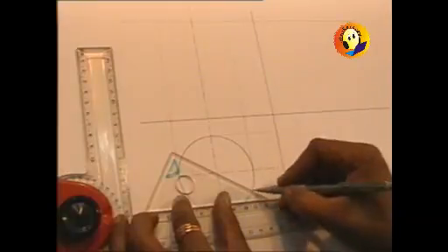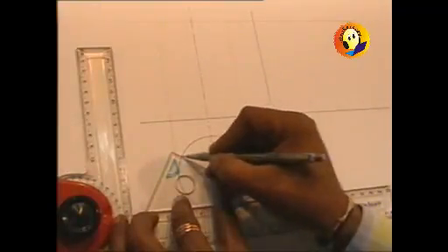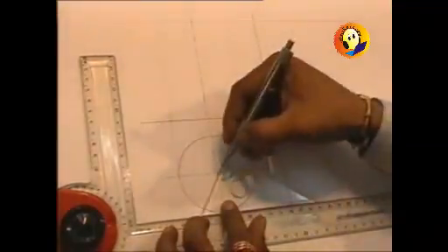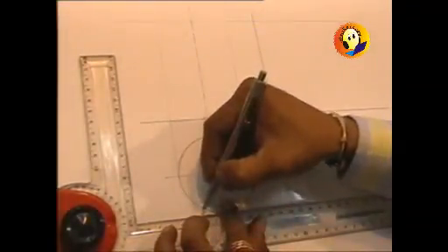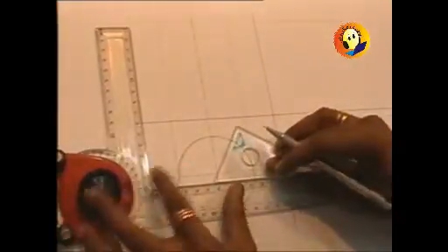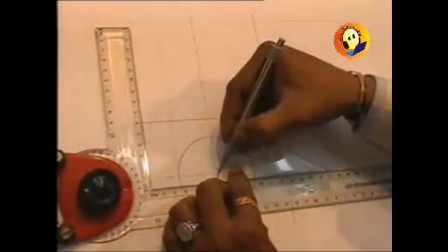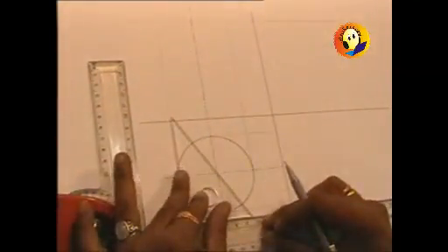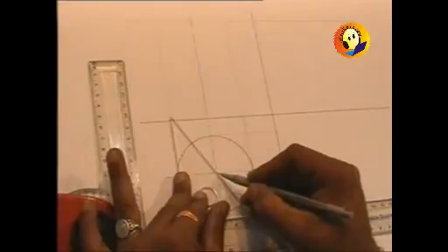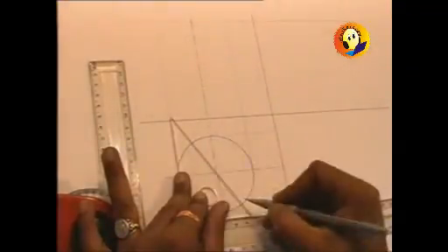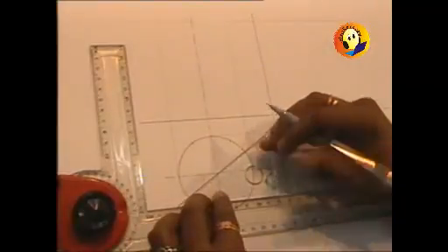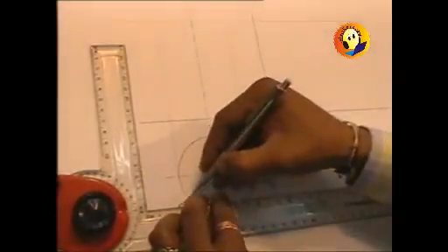We will be making use of the set square only, the 30-60 set square, so that we can mark the 12 parts using the set square. That will be faster. So just mark the points. It will be easier as well as faster. Use of compass I am trying to eliminate to improve on the speed, and so we get the 12 parts of that circle.